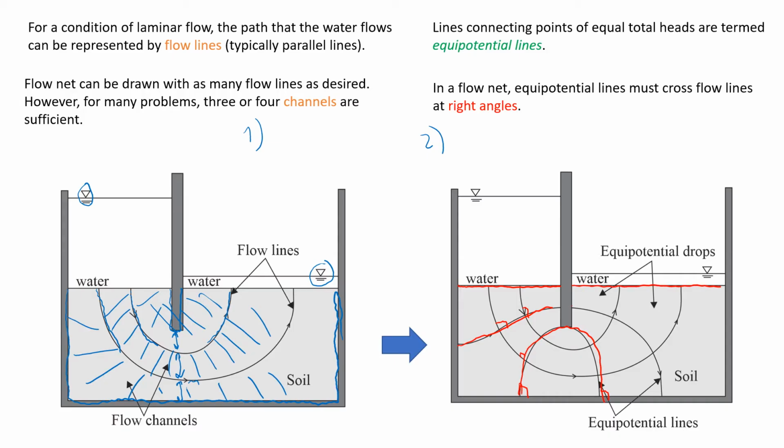So these are equipotential lines, which means that there is no water flow if we put point A here and point B here. There is no water flow between these two points. Again, we will follow similar rules: the distance between equipotential lines should be more or less the same, and we would like to draw nice squares.